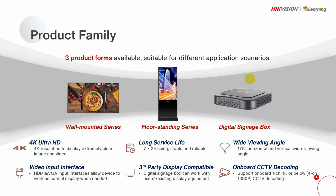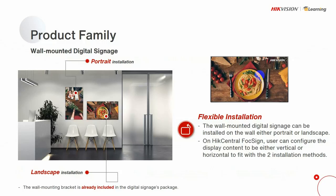And the digital signage supports onboard one-channel 4K or below, which is actually 4-channel 1080p CCTV decoding. Okay, so you have to watch out for the decoding ability of digital signage. For wall-mounted digital signage, you can have flexible installation. It has two types of installation: portrait and landscape. Of course, in the centralized software HikCentral FocSign, for example, HCF, the user can configure the display content to be either vertical or horizontal to fit the two installation modes.